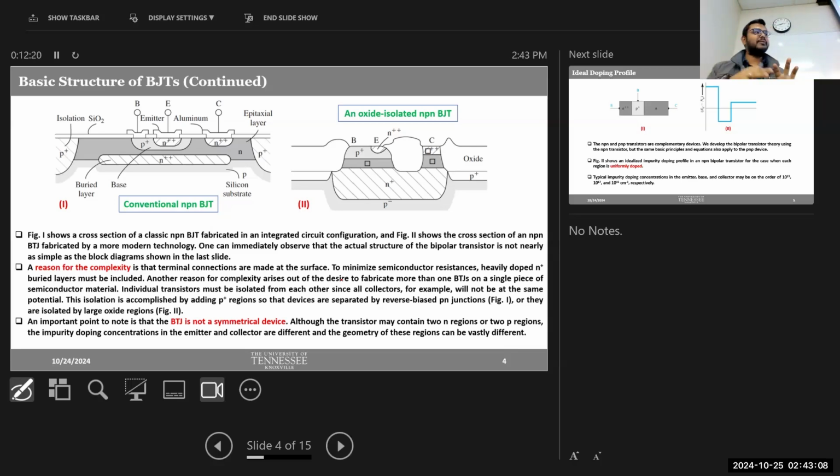But when we make this device in hardware, when we fabricate it, we don't have the freedom of having a terminal anywhere we want. When we make this device, we will have to create contacts. We call them contacts. Each contact will be a terminal here, right? For each terminal we'll have to create contacts, and the restriction is that we can only make contacts on the surface of the device, because after fabrication, when we perform measurements with that device, we can access those contacts and apply voltage or measure current. That's the measurement process, so we need to make those contacts on the surface only.